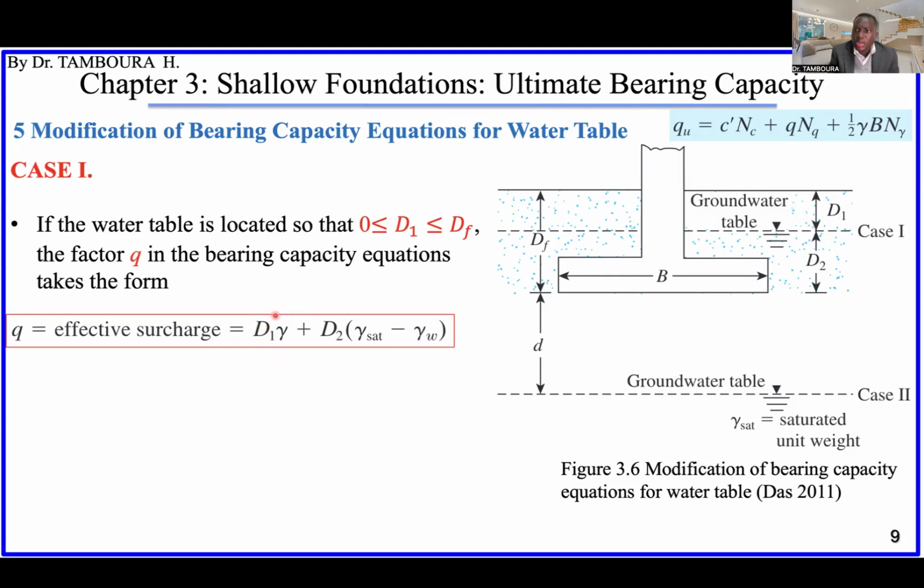Then we have to add the weight of this soil. As you know, water is helping to support load. The weight of this soil, the saturated soil itself, is heavier than the one here. But the stress that this will cause will be partially supported by the water.